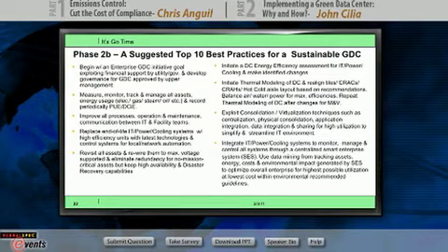You want to initiate the data center energy efficiency assessments. This is very important, as we talked about under phase 2, to get all your assets and make all the measurements. You want to be able to get your thermal modeling, if possible, of your data center by reading your air and water temperature throughout the data center, and afterward come up with some different scenarios to figure out how you can do your CFDs.